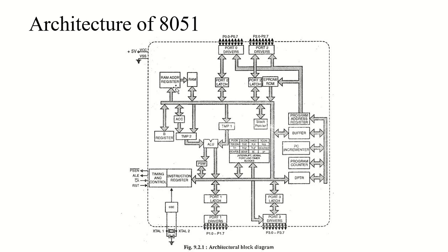One more point, after a reset the stack pointer is initialized to 07H, right? So the question is, at what location will the stack begin? If initialization took place at 07H, then the stack will begin at 08H.